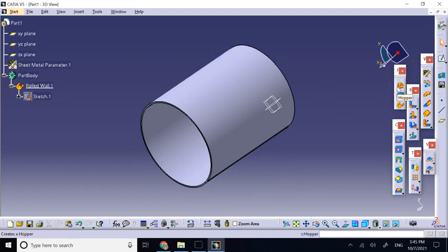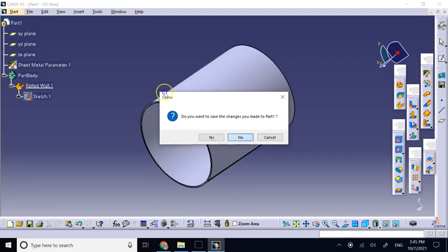The other one that you can do, more complicated than a cylindrical, is a hopper. Here you can create a sheet metal, but the sheet metal looks like a multi-section, right? So this cross section of it is going to be different at different depth values, right? So in order to do that, you need to first create a surface. You go to Generative Shape Design, GSD, create a multi-section surface, and then use this hopper to fit a sheet metal to that surface. So let me show you that one as well.